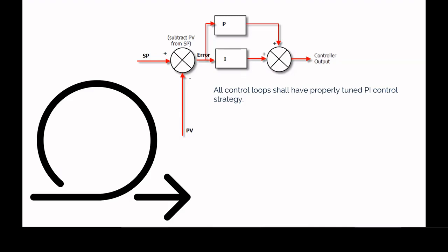So what the PID loop does really is to introduce something called integral. And the best way to think about integral really is to think about how long the valve needs to be open 100% in order to not overshoot the set point. So as an example, if I'm saying I need the supply water to be 70 degrees, how long does this valve need to be open at 100% for that output to be satisfied, or the set point to be satisfied?